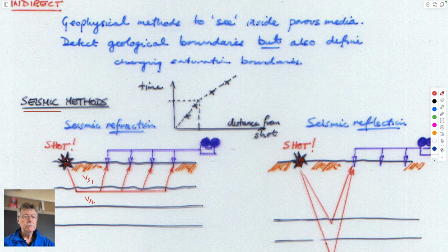The idea is that you can put geophones out on the surface. These are just seismometers that are a weight inside a cage, an electrical cage. When the weight swings, because you're exciting the outside of the housing, it puts up an electrical current in the surrounding coil, and that's recorded as basically what you'd think of as a seismometer trace.